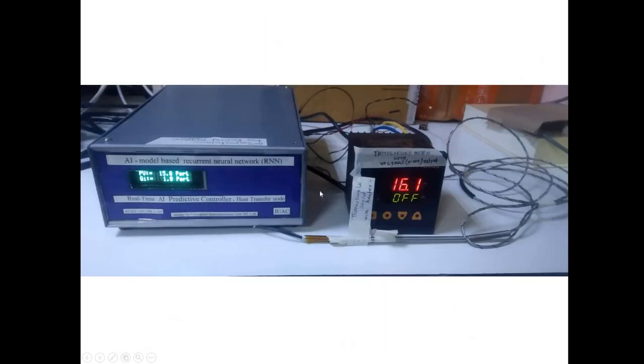Writing 0.5 means it will write 50% power into the device. As I said earlier, the yellow one is the heater, a small heater, and this is the thermocouple sensor. This is the temperature meter. The temperature value is read into this first box, and after that the power you are writing into the heater is right now 1%, almost zero power is going, and 15.8 degrees is being read back, and this display changes every second.